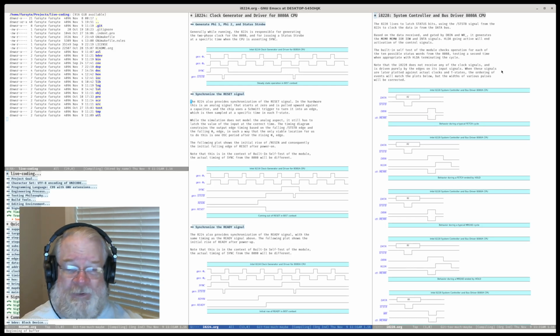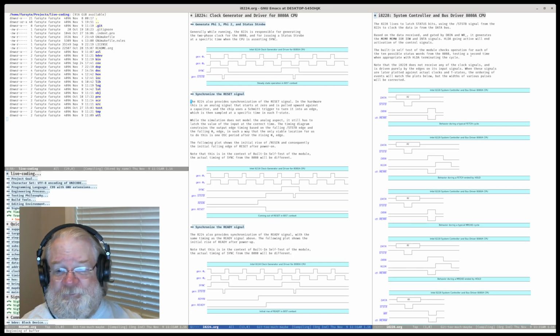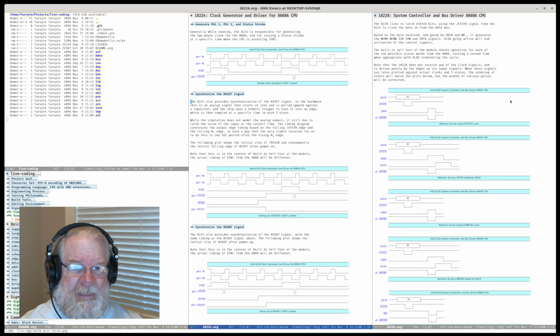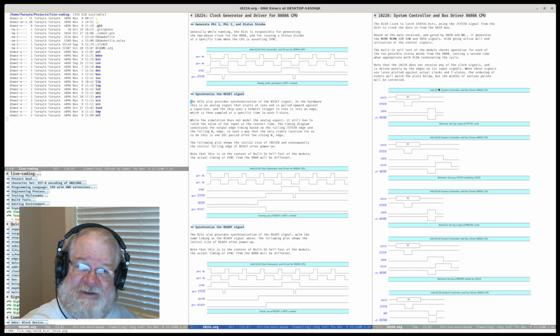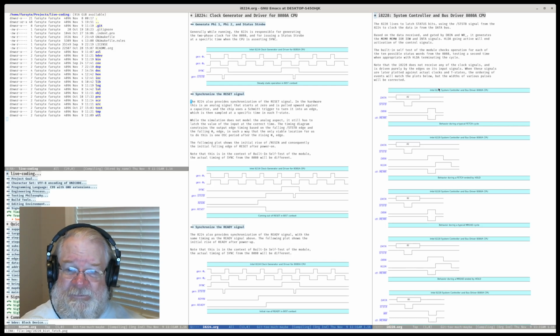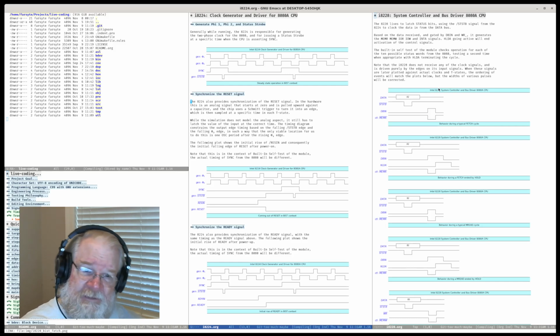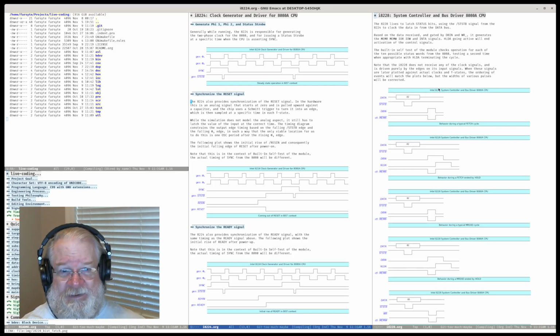Are we in halt and so on? There's a whole bunch of status. It's like a dozen combinations of these 8 bits that make sense. And its activity is defined specifically for those combinations. It says, if all 8 bits are in this pattern, we do this. It's not defined in the documentation as this output signal is this Boolean logic of these input signals, okay?